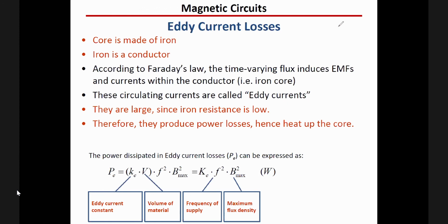So what is the problem here? No problem. But if you have magnetic field inside the magnetic core, and if you remember Faraday's law, which is basically that if you have magnetic field and a conductor, current or voltage will start to be induced, right? So this is what is happening inside the magnetic core. We have magnetic field in this cross-sectional area. Because we have magnetic field and also a conductor, voltage will start to be induced inside the magnetic core. Is that a problem?